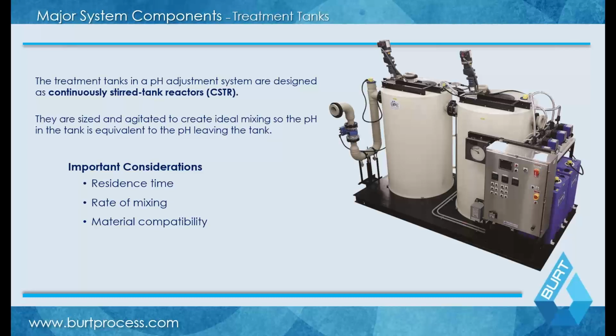Because of that, pH neutralization systems are typically sized for the maximum flow rate that you could see into them. Now, when we say continuous system, or even a hybrid style system, the waste does not have to be continuous all the time. So you may see peak flows of 50 GPM, then drop down to 30, 0, 10, back up to 50. You're going to have a 50 GPM system at that point.